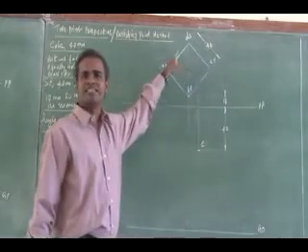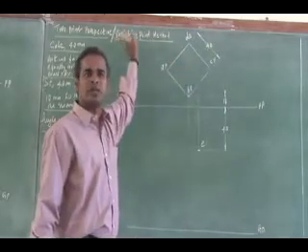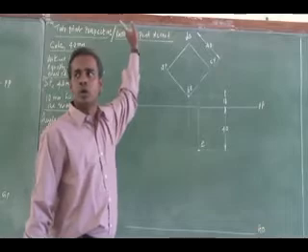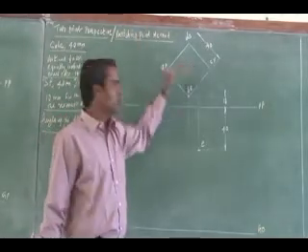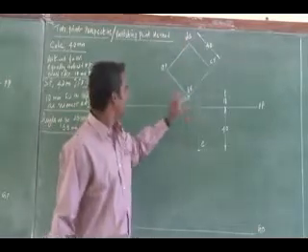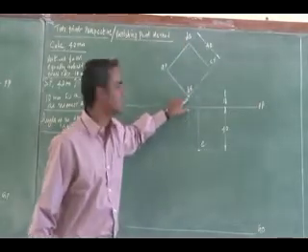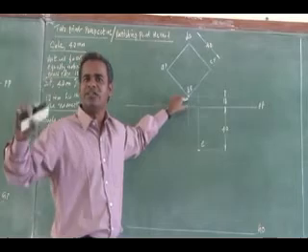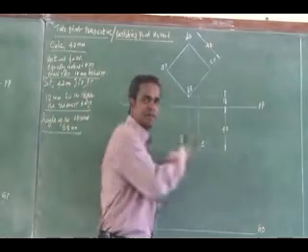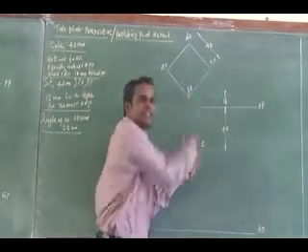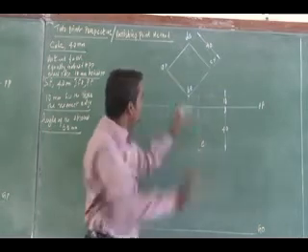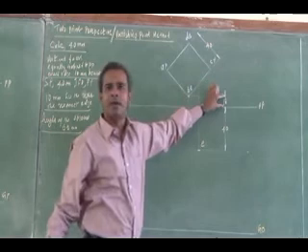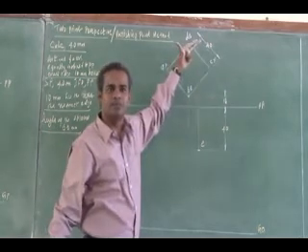If you are going for the vanishing point method or 2-point perspective, you see here, the top view I have drawn, the faces are equally inclined. BQ is going to be my nearest vertical edge. Station point is here, observer is here. For him, the nearest vertical edge is BQ. That BQ is 10 mm behind the picture plane.